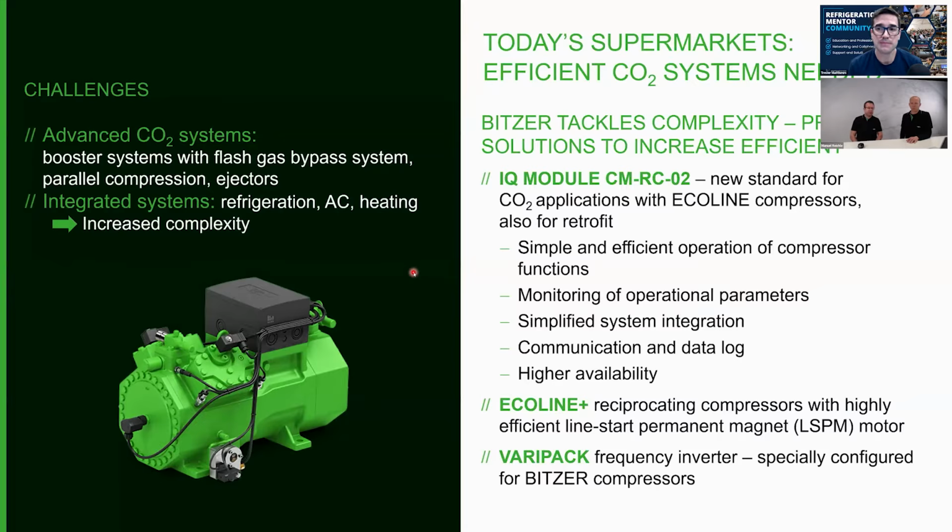At the end of the day, the oil separator is not separating 100% of oil always, so there's always a little bit of oil going into the system, which was not coming back because there was no running time, and the service technician was then called for lack of oil in the compressor because of the oil management system. They could not feed back the oil. So what they did is they refilled oil and the system was running.